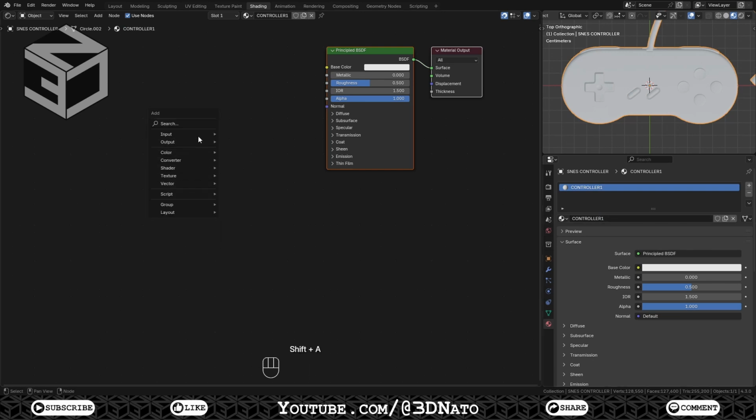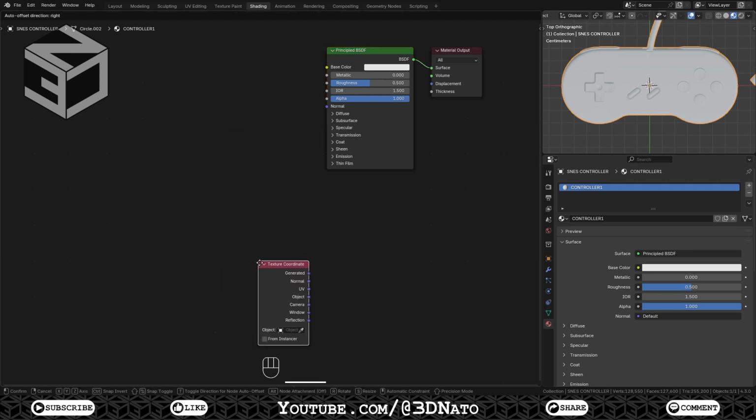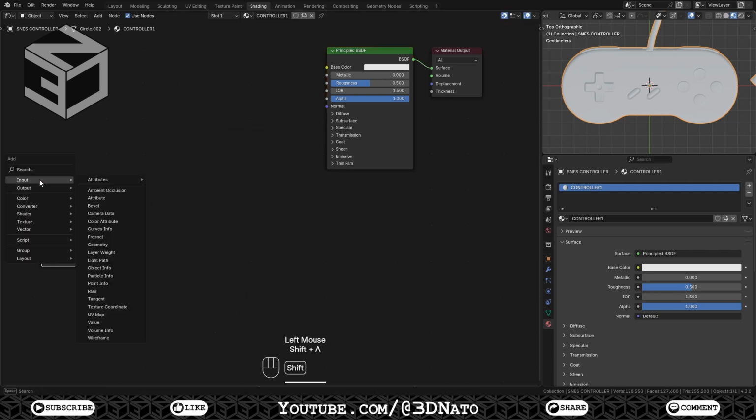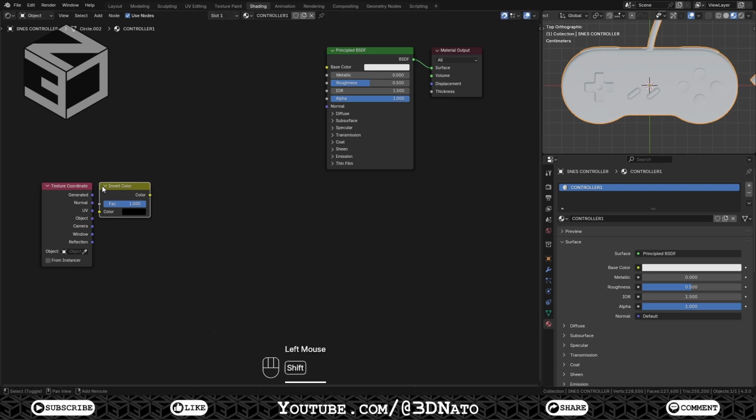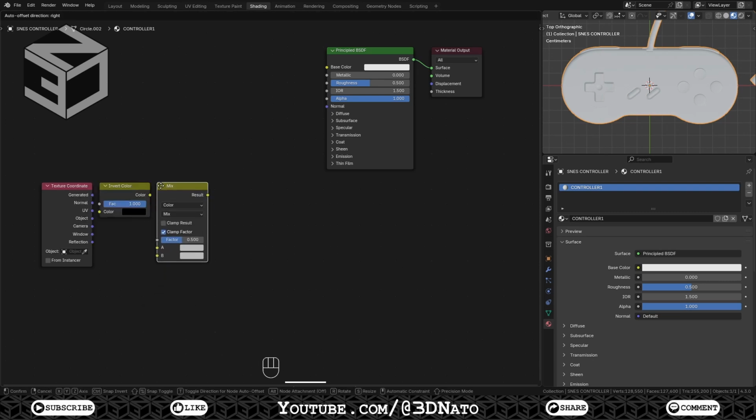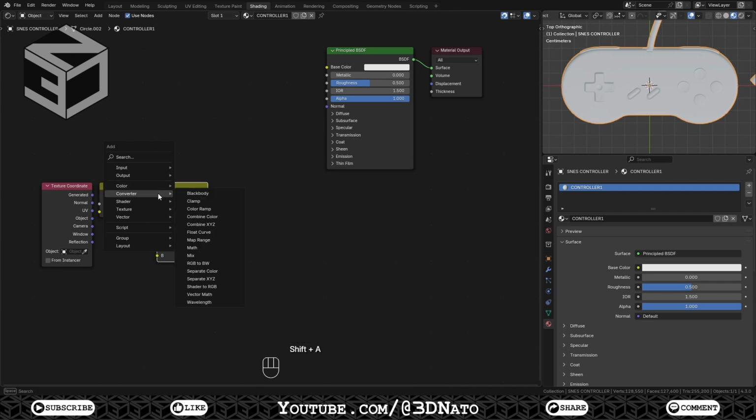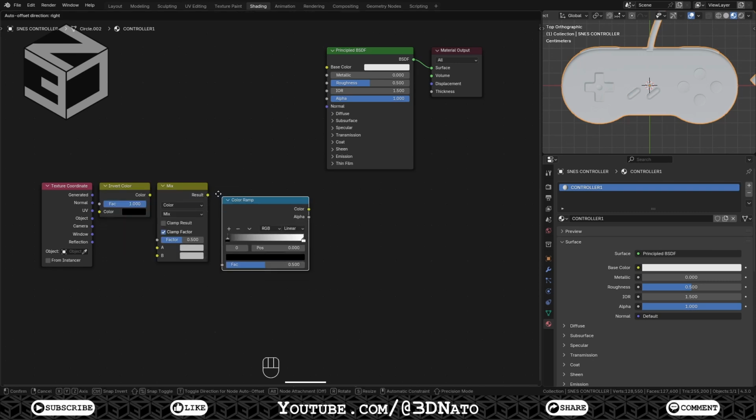Press Shift plus A, go to Input, and add a texture coordinate node. Press Shift plus A, go to Color, and add an invert color node. Press Shift plus A, go to Color, and add a mix color node. Press Shift plus A, go to Converter, and add a color ramp node.